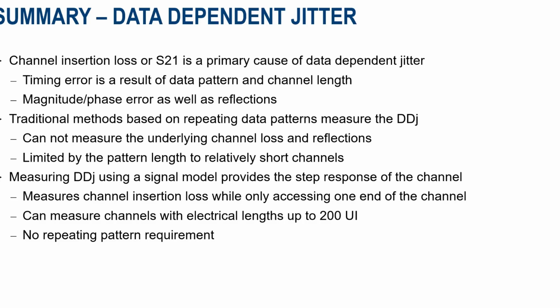And I should add that the model-based method allows one to measure the insertion loss directly by just accessing one end of the channel. And we can measure channels with lengths up to 200 unit intervals with this methodology. And there's no repeating pattern requirement. Using the model-based method, it will work on random data in an active channel, which makes it extremely flexible and helpful in tracking down and measuring these data-dependent sources of jitter.